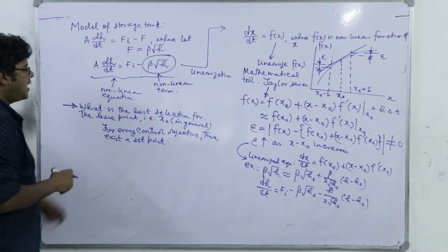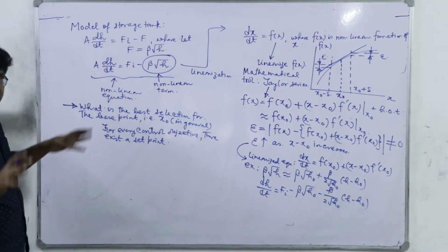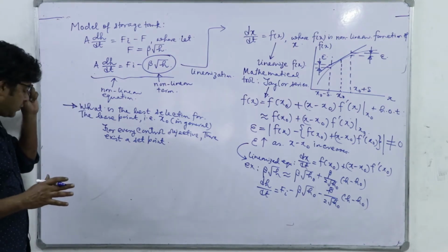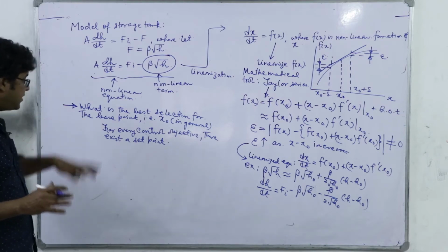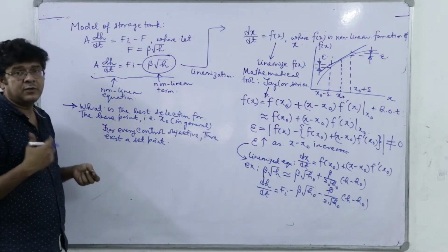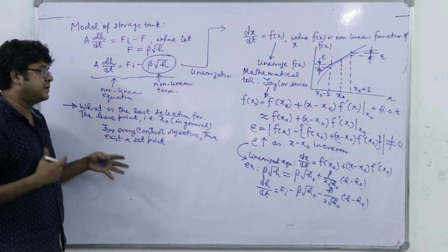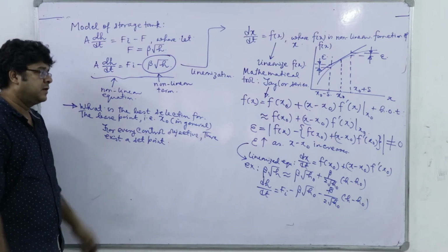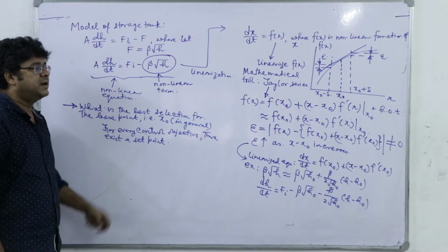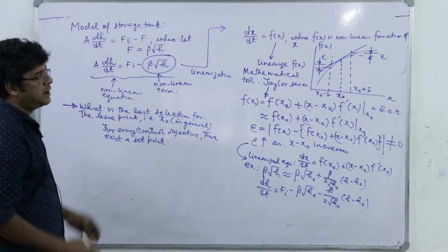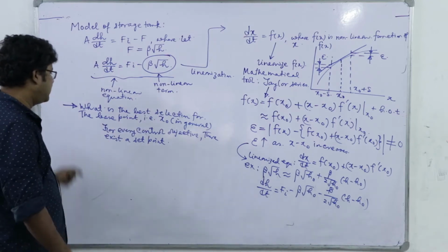And if it is fitted with a controller, which actually is our objective, that we have to design a controller with appropriate parameters such that the h is always, even if it deviates from this set point, close to that set point, right.